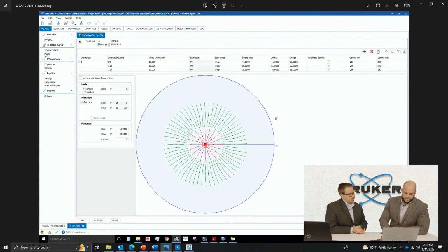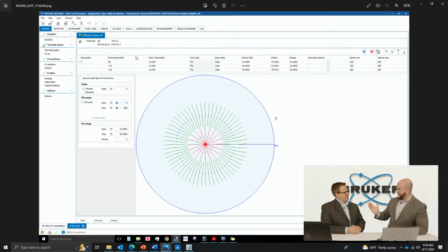The next step you would go into Texture Basic, and you would design your experiment for each reflection with the pole figure that you want. So you'd have to have some knowledge of where you're expecting crystallographic reflections. And if you don't know where those peaks should be? If you know nothing about your material, you can do a simple powder scan. That'll give you some idea. Again, if you do have preferred orientation, you might miss a couple of peaks, but...